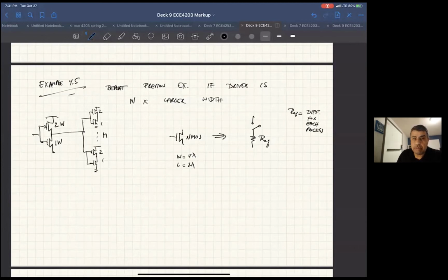Now, remember the NMOSFET, when it turns on in an inverter, does all sorts of crazy stuff. It goes into saturation mode, then into linear mode and all that. Our delay model isn't meant to fully model each step along that process, but the overall delay.